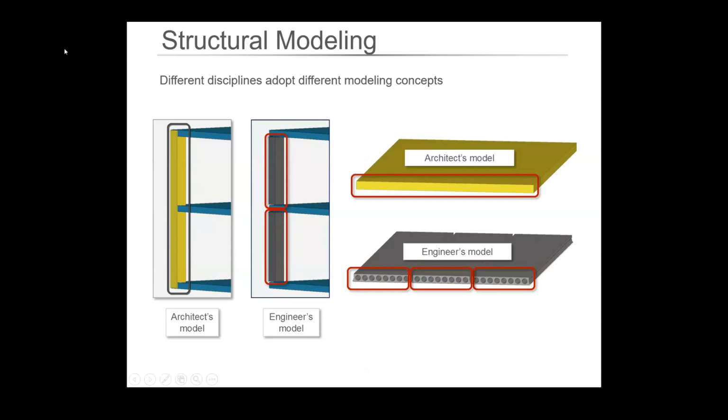So sometimes we model a wee bit differently. So in our case, although we've gone away from this, we might model columns stretching for the entire length of the column, so it goes across stories, whereas an engineer's model will have them separate, which is tending to what we do now. Things like floor slabs, we model as just a generic slab of a certain thickness, whereas the engineers start putting these hollow core slabs in slab by slab, element by element, so they have lots of slabs in their model, whereas we've got one to do the same job.